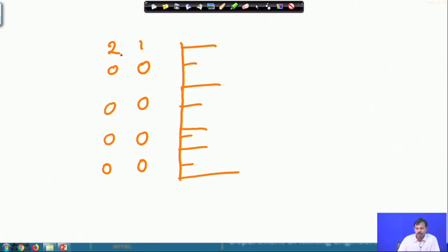If you are considering this case, then the rock resistance from this first row of hole is this much and this is called burden. However, if you are looking from this side, there are 2 holes in the first row of holes and this is the first hole, this is the second hole and the distance between these 2 adjacent holes is called spacing.